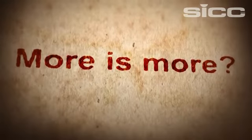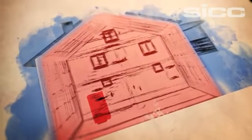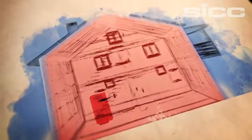So in order to get the lowest U-values, the heat resistance of the shell has to be improved. Subsequently, the energy consumption falls. This may occur when an additional layer of insulation is added to the existing facade, or if, during construction, building materials are used that offer better insulation value.